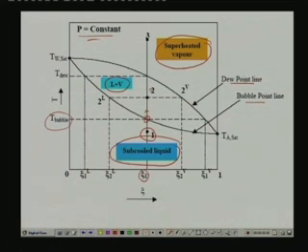So, if you heat it further, you have entered into the two phase region, that means you have both liquid as well as vapor. If you continuously heat it, you arrive at a point at which the last liquid droplet evaporates, as I have already mentioned. And this temperature where the last liquid droplet evaporates, as I told you, is nothing but the dew point. So, you can read the dew point and bubble point from this chart. What is interesting is the two phase region. See, if we started with initial composition of zeta 1, then in the subcooled region the concentration is zeta 1.